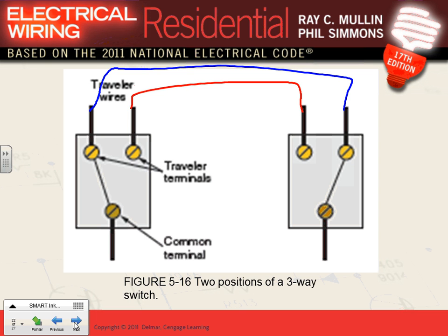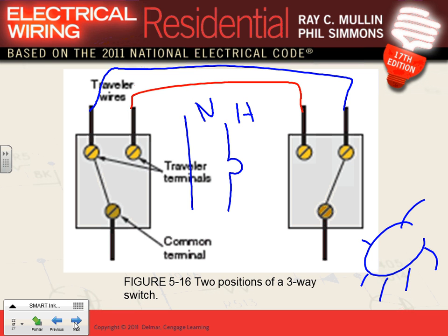And from this side, if I have a fixture, a light here, okay, now I want to ask my friend Andrew, you're going to decide: do you want to take this side to the light, or to the switch? Here's the circuit breaker right here, bringing the power, here's my hot, and here's my neutral. Depending where you are located physically, can you bring this one to the light or to the switch? Since we're closer here to the light, what do you think the best way to do is? To bring this one to the light, right? And if I brought this one to the light, I have no other option. This has to go to the hot, okay?